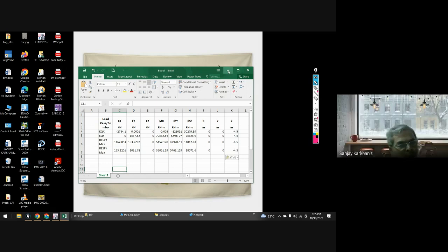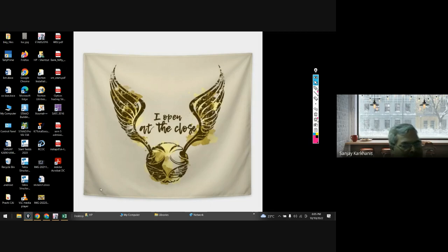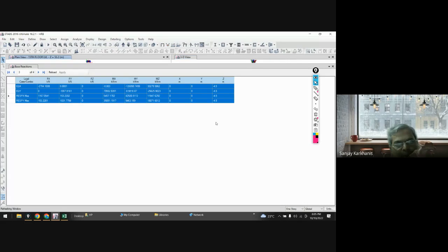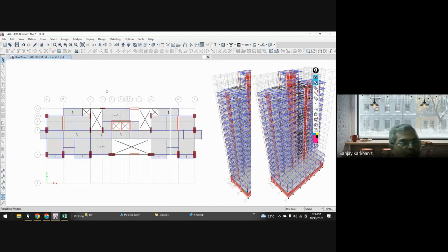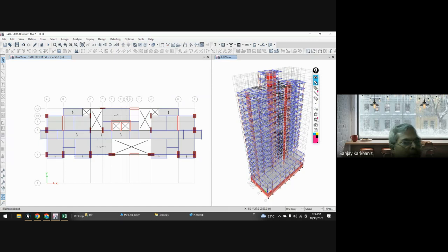Then I will put it down. Then I will reopen this, and now I will close this. And now I want to make a correction in the scale factor. For that, I have to unlock it. Now unlocking will delete all the results. That is okay, because unless you unlock it, you cannot edit that scale factor.